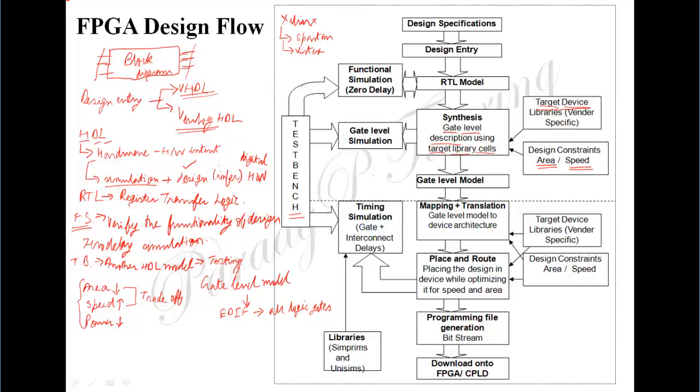Sometimes beforehand, although we do not generally perform this in case of academics, it is always better to perform one more simulation after synthesis, which is called post-synthesis simulation, and this is also called gate level simulation. For the simple reason that, at this point, the design also incorporates the propagation delays, which are gate delays, along with the design. So we perform the gate level simulation using the same test bench which we used earlier, and we'll have to match it with the design specification to see whether the design is meeting the requirements or not. There are several factors which decide whether the design meets the requirements. So that's the gate level simulation.